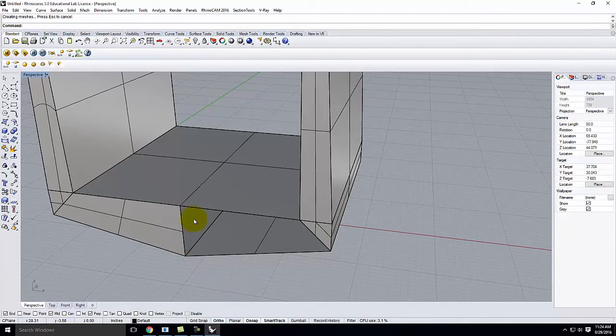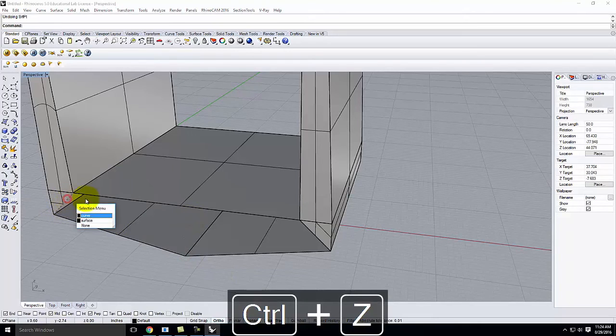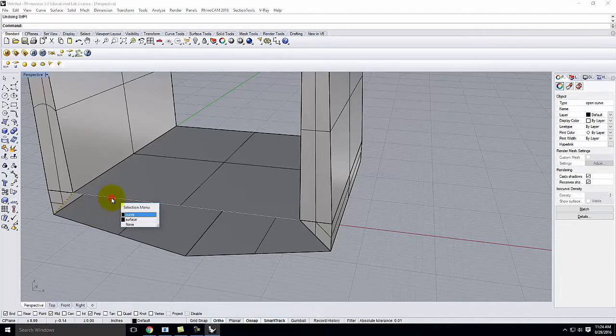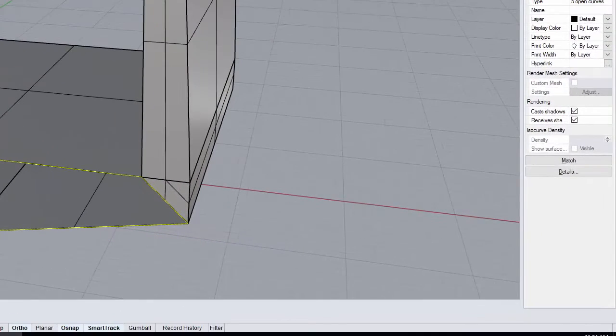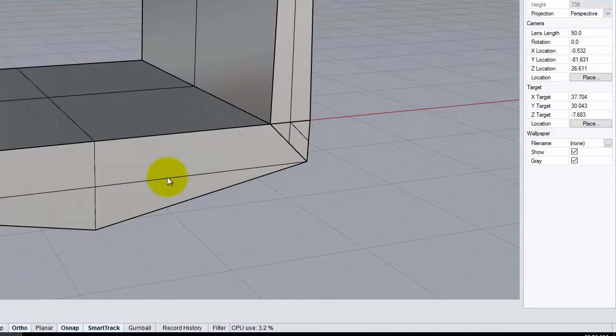That would be fine. Or I could select all the curves that go all the way around. So we'll take this, and this, and this, and that, and that. They go all the way around and go up to Surface Patch. So in this case, I have 5 curves that represent the bottom, and I've made one surface out of those. So there's just a variety of ways of creating it, right? And I'm trying to show you different ways of trying to work through this, because as soon as you get an exercise or an assignment where you have to model it yourself, you have to come up with, how do I model this? Right? Right now it's scripted.